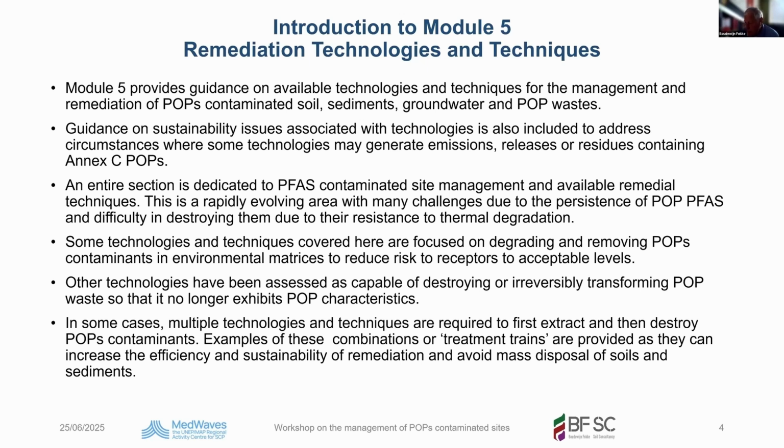The clean part is in this case the fraction which is larger than 63 mu, and the contaminated part is the fraction which is smaller than 63 mu. And of course the volume of the soil to be treated is then less, because you concentrate the contaminated part of the soil, but then the concentration is of course higher.